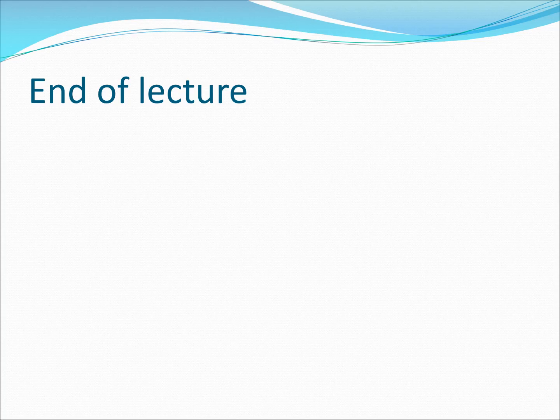So I'll end this lecture today, and in the next lecture I'm going to take the last matrix which we looked at, which had 21 coefficients, and I'm going to see how that matrix essentially becomes simpler for orthotropic materials and becomes really simple when you have isotropic materials, because in isotropic materials you have only two material properties, and they are going to be the Young's modulus E and the Poisson ratio nu.